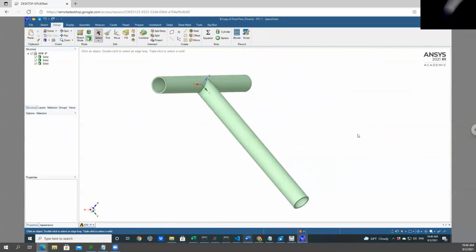But the thing is, we are done with this basic step. Can we extract a volume out of this complex geometry, right? Because again, if you transfer this to ANSYS, it will think that you want to model heat transfer on the solid, right? But we don't want to model heat transfer on the solid. We want to model blood flow going through the volumes. So we need to extract the internal volume and pass that to ANSYS. If we can, then we are done with this step, and then we can move to another more complex step, which will be creating the hemispherical geometry.